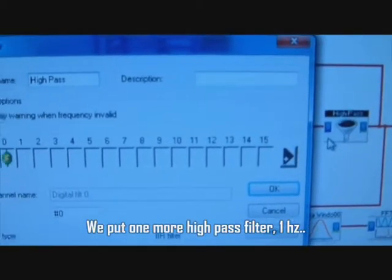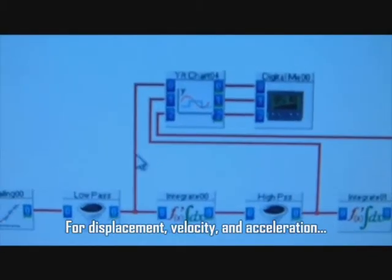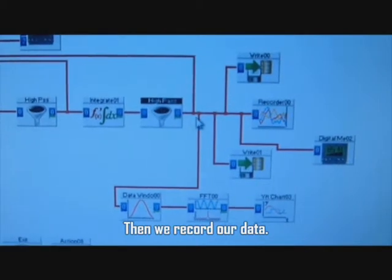We put one more high pass filter, 1 Hz. For displacement, velocity and acceleration, we display using YT chart and digital meter. Then we record our data.